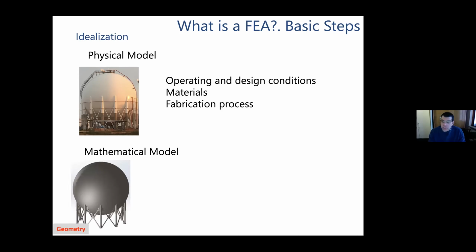So first of all, we start with the geometry, okay? So basically the representation of the geometry. Here's where you decide if I want to represent my spherical tank just by a sphere, if it's a shell, if it's a solid, if I can actually remove all the supports, or if I should include them in the mathematical description. Then comes the modeling framework. The modeling framework comprises the governing equations, which is basically a set of partial differential equations that will govern my solution, and the boundary conditions.